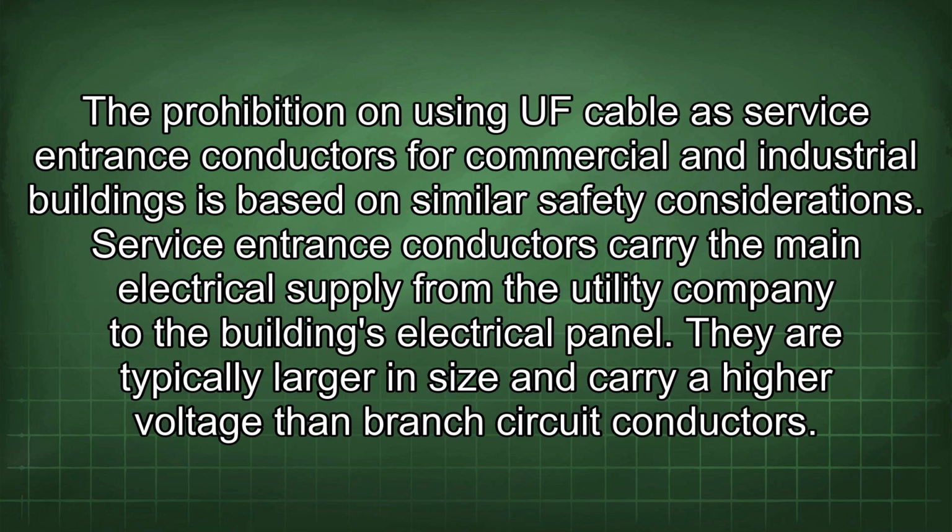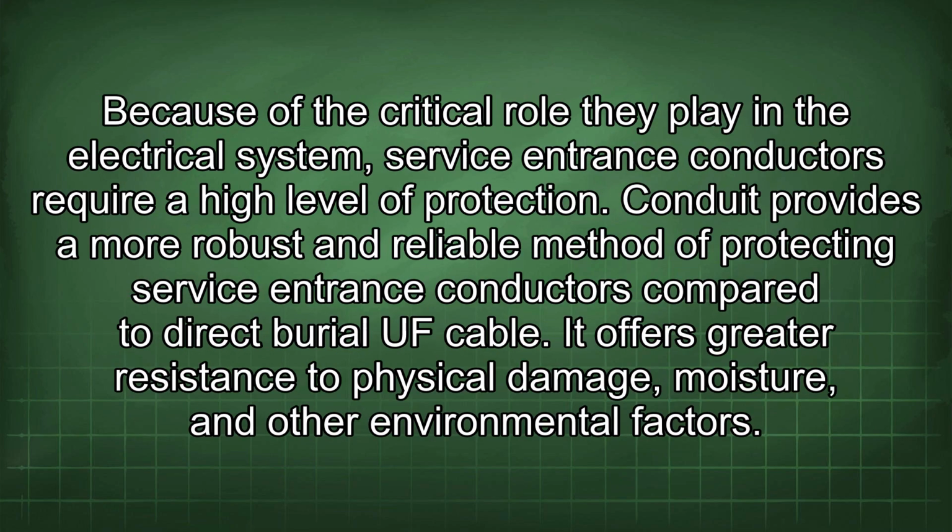The prohibition on using UF cable as service entrance conductors for commercial and industrial buildings is based on similar safety considerations. Service entrance conductors carry the main electrical supply from the utility company to the building's electrical panel. They are typically larger in size and carry a higher voltage than branch circuit conductors. Because of the critical role they play in the electrical system, service entrance conductors require a high level of protection.